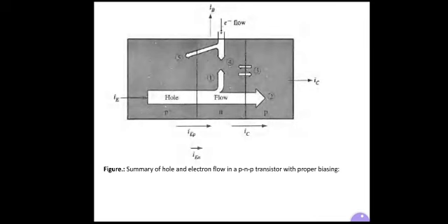So the dominant sources of the base current are two: first, the recombination in the base, and second, the injection into the emitter region. Both of these effects can be greatly reduced by device design. In a well designed transistor, IB will be a very small fraction of IE. Remember, base current is very negligible compared with the emitter current.